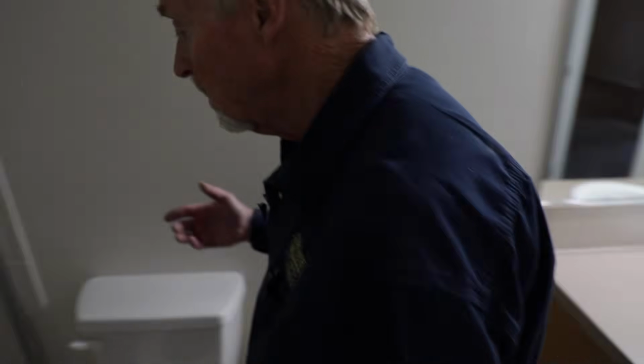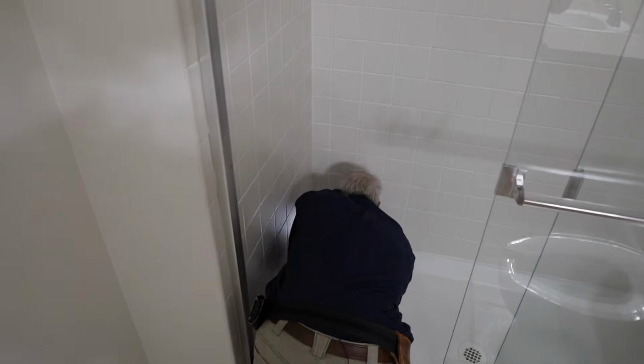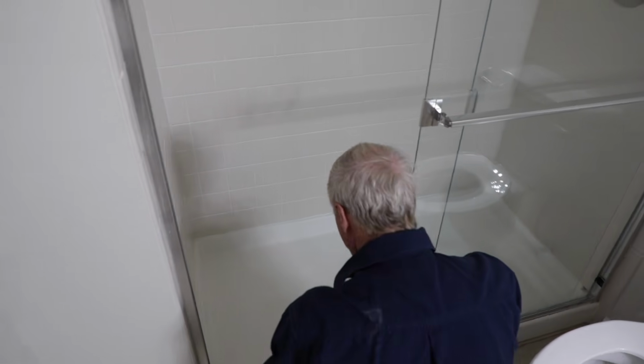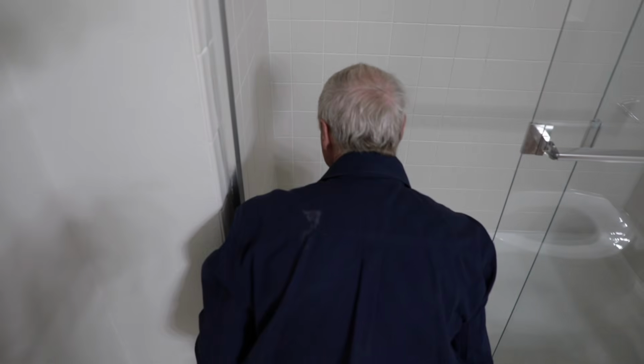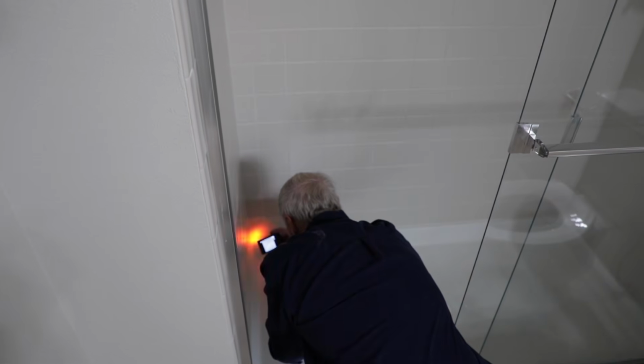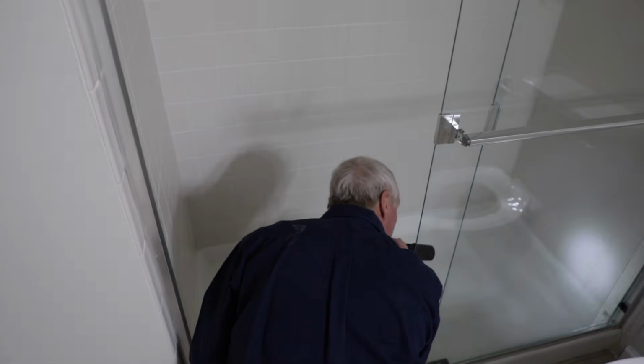I'll come over here to my shower and I start with a visual inspection of it. I'm looking to see, do I have any issues? And I have a minor one here with a crack in the pan that looks mostly superficial, but I'm going to take a photo and make a note of that in the report so that a client will know that I saw it and did not think it was a big deal. Could use a little caulking repair in that same corner, but it's pretty minor.